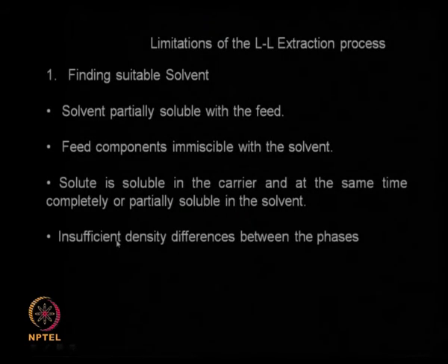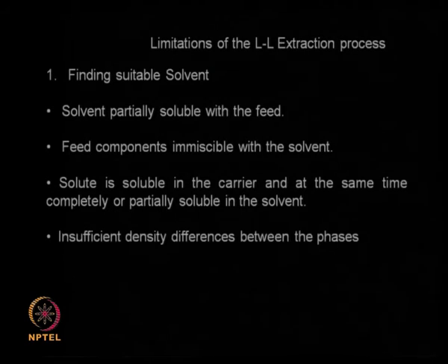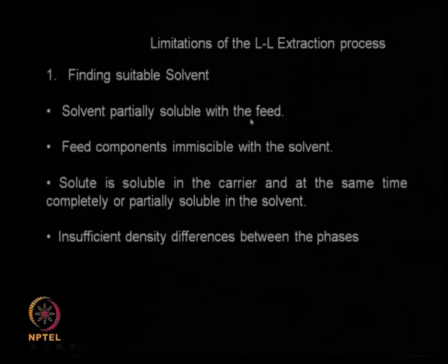If the density differences are not much, then you are not going to get two distinct clear phases. So, these are some of the limitations of liquid extraction. What happens if the solvent is partially soluble in the feed? You are going to lose some solvent.